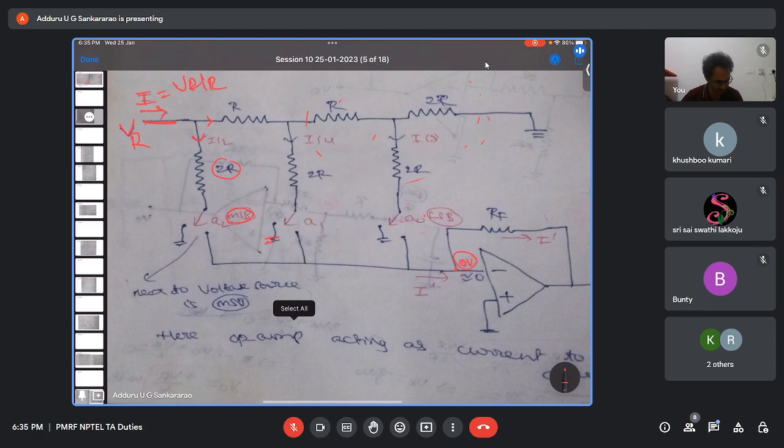And another side you take, let us say all are connected to this. Now if you see here, these two are parallel, R. So this and this are series, 2R. Again these two are parallel, R plus R, 2R. So overall you'll get 2R. So the current is facing equal resistances, 2R and 2R. That's why it will be divided equally, I by 2, I by 2.